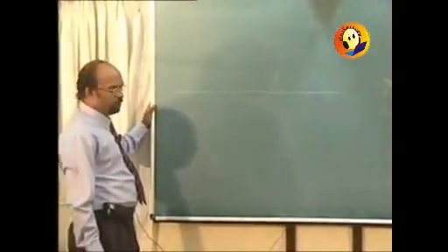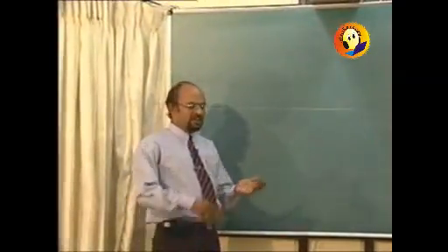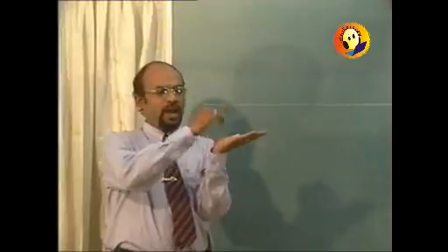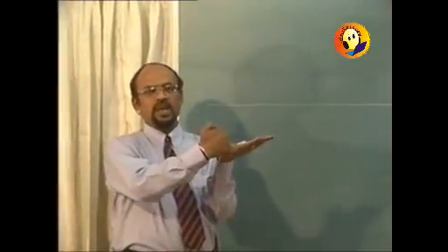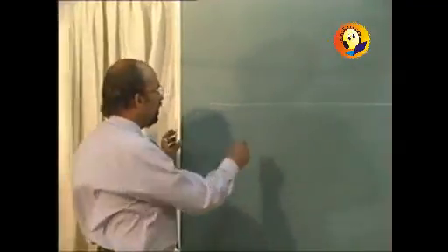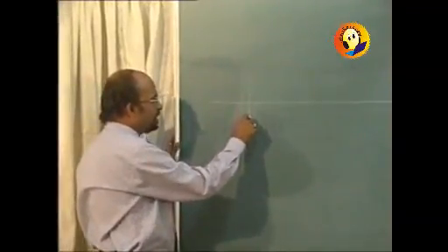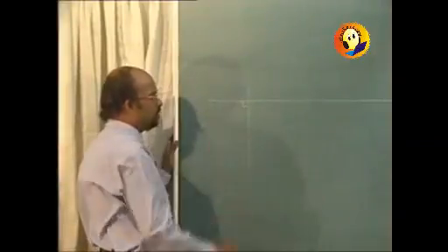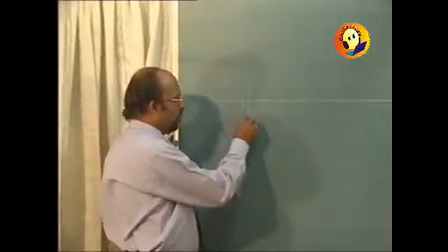as the lamina is going to rest on side AB in HP and it is making some angle with HP, you can always remember that the lamina should be kept in HP and then should be rotated, and the line of rotation, that is AB, because that line is not going to move at all. So we will consider AB as the line of rotation, and the line of rotation should always be considered perpendicular to XY.